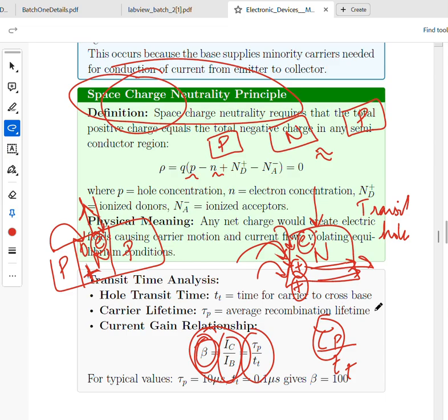If the recombination rate is high, if the transfer rate of the carrier is very low, what happens? That means holes are able to transfer very fast, faster than they can recombine. So it transfers, and at some point the recombination will hit and it will recombine with the electron, and a new hole will come. Since a new hole is there, again for charge neutrality another electron will enter because the previous electron was recombined.